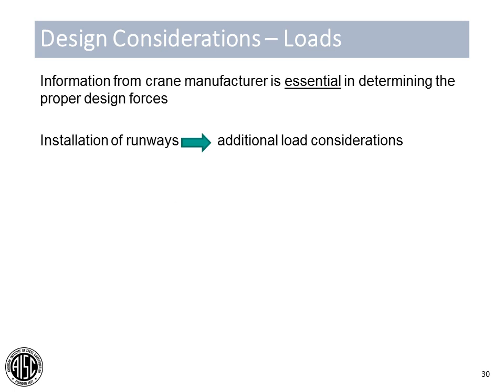So not only is the information from the crane manufacturer essential in determining these proper forces, but the installation, as I mentioned, of these runways can lead to a substantial amount of additional load consideration. This is not only at the initial installation, but also throughout the service life of a crane system. It should be noted to the owner, make sure they are aware that regular maintenance and inspection needs to be considered during the service life of these cranes to make sure late in life we're not accidentally imposing unanticipated loads on these systems.